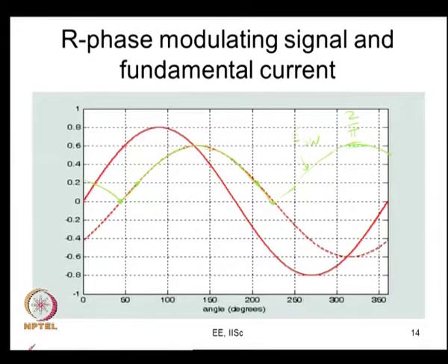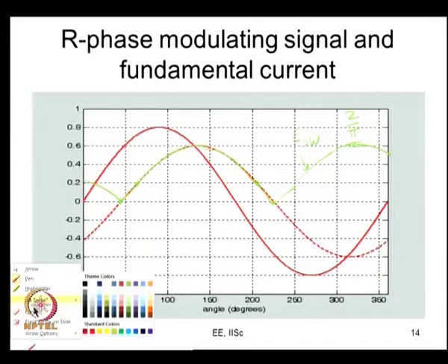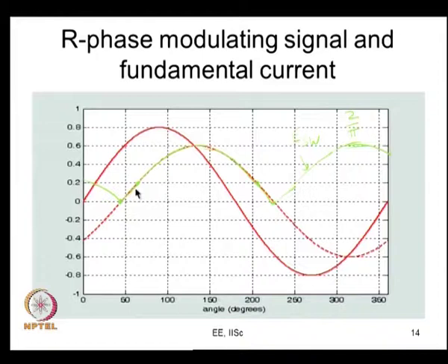And the significant thing that you can note down is, now let us say the current waveform has the same amplitude, but a different power factor. Now, the current waveform may be at a different phase angle. Here it is shown at 45 degree lag. It may be, let us say, 30 degree lag or whatever lag. So, what is going to happen is your ESW is going to be similar to that. That is, the wave shape is the same as the rectified fundamental current. It is only going to have a phase shift, but it does not matter, the average value will continue to be the same.